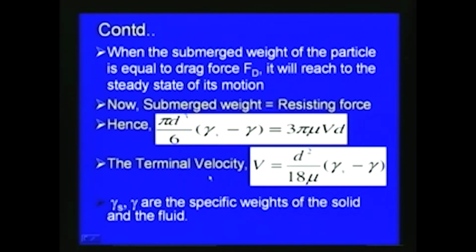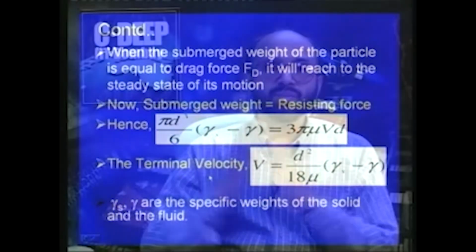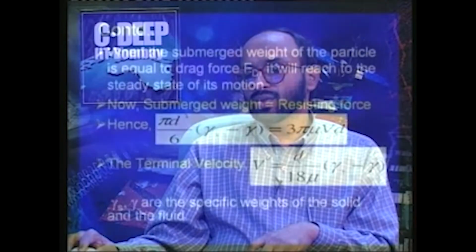This has applications in a number of fields, as I mentioned, like reservoir sedimentation or dust particle analysis in the atmosphere. We can use this Stokes law in a number of applications. It was derived by Stokes in the 19th century. He approximated the Navier-Stokes equation and simplified it so that it can be applied to very low Reynolds number problems.